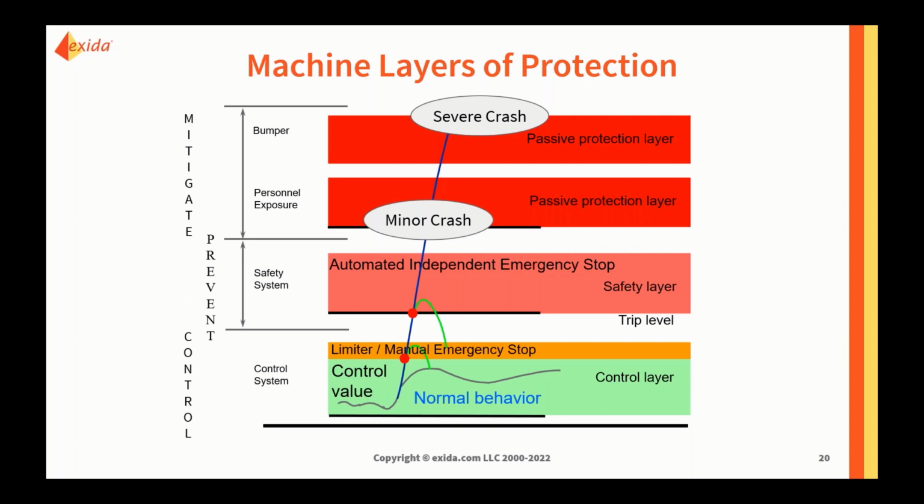And if that automated independent emergency stop is required to either act continually or sense the behavior of that system on a continual basis and be always ready to stop and actually activated on a frequent basis, then that safety function will be acting effectively in high demand mode, and its failure rate is the best way to express our initiating event frequency and understanding the overall potential accident frequency that we're trying to analyze.